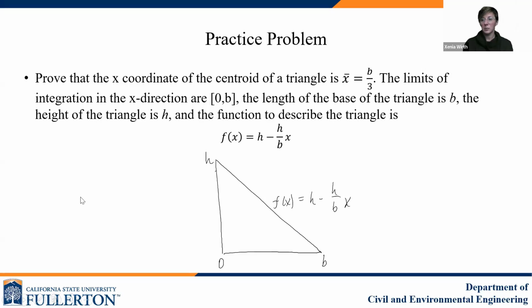I encourage you now to practice what you've learned by applying the second application of integration. Prove to me that the x-coordinate of the centroid of a triangle is b over 3. This is something you'll be using in statics, mechanics of materials, a lot of classes where we see triangular distributions of loads and things like that. It's good to know the centroid of the triangle.